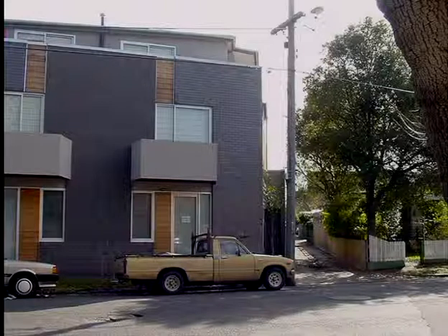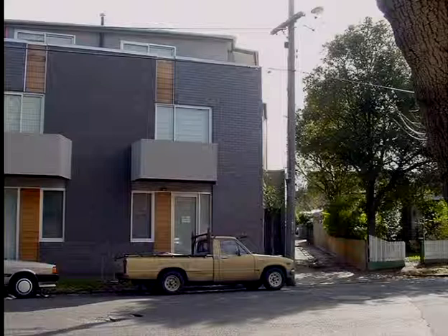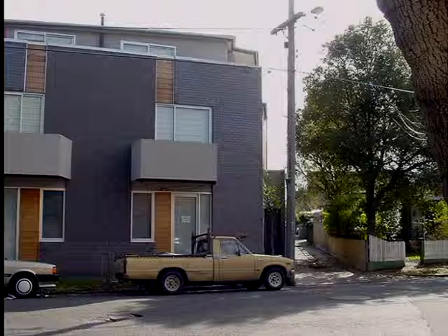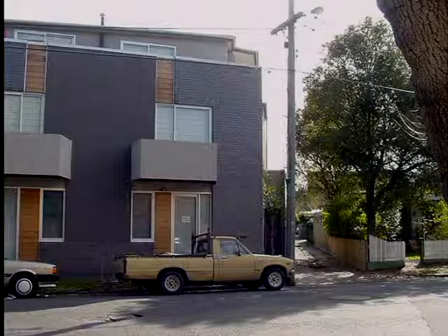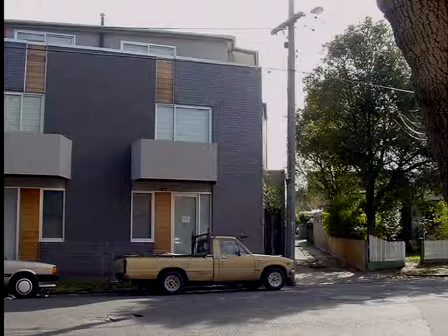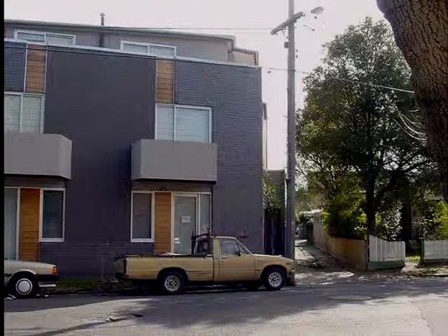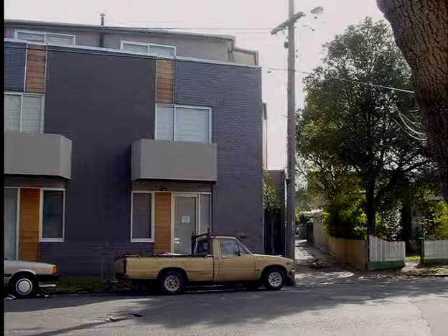Okay. Now, why is that important? Because we need to know the width of the driveway to generate a car turning circle. So the distance that your building has to come back to allow a car to come in, because we have a very narrow laneway, is something you need to account for. Otherwise you can't get the car in, and the client won't be very happy about that.